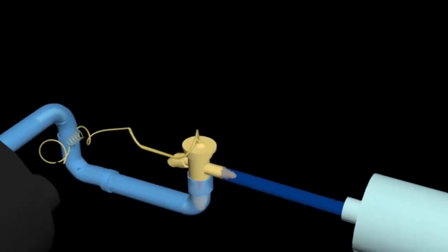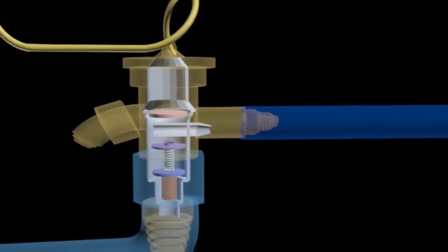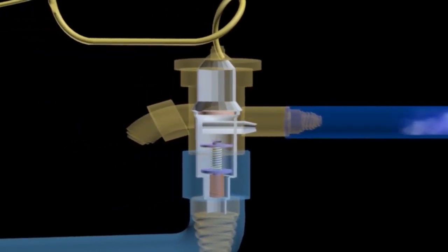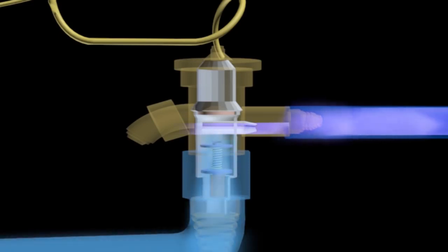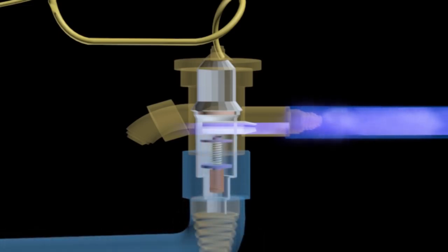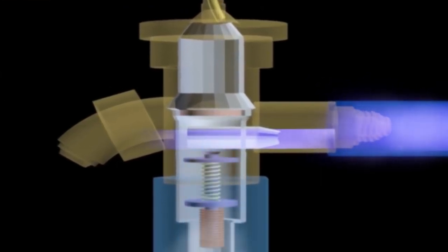Expansion valve. Expansion valve serves to reduce the pressure and control the flow of refrigerant going into the evaporator. When the pressure of refrigerant has declined drastically, the temperature will drop dramatically, which is lower than chilled water temperature. In a centralized system, expansion device DXV thermal expansion valve type is used.